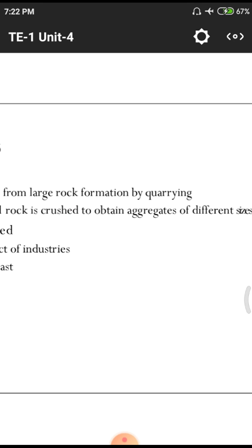After the required sizes are obtained, we allot them to different uses. For construction purposes, boulders of normally 40 to 60 size rocks are used for filling the ground surface. After that, 40 size aggregates are normally used for the construction of slabs. 20 size aggregates are also used for beams and others. 10 and 5 size aggregates are normally used for filling purposes in different utilities of construction.